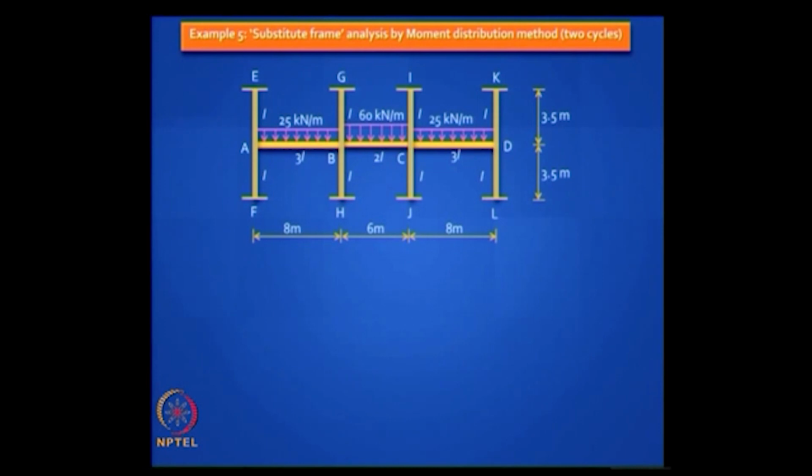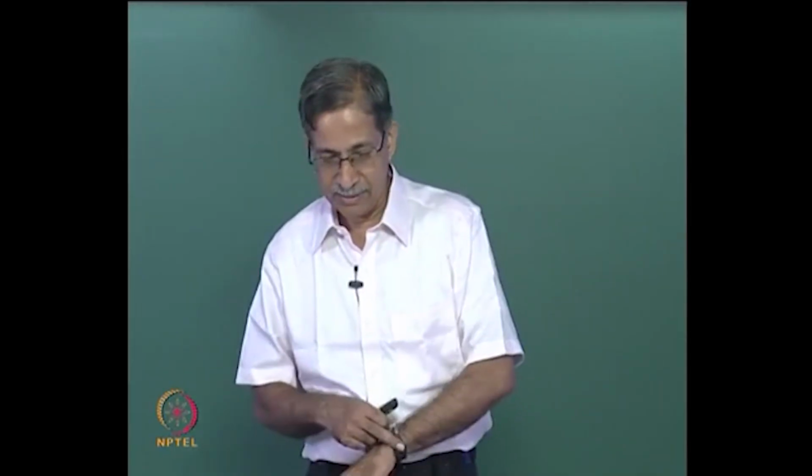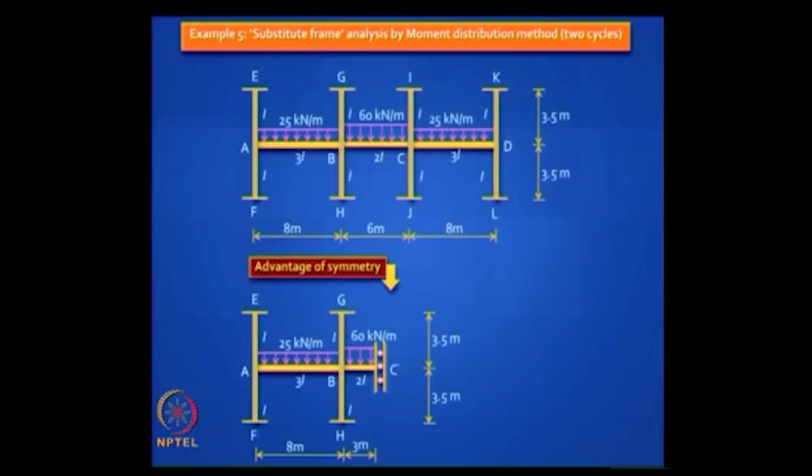So that is what this is, for example, what you can do in a 3-bay multi-storied frame under gravity loads, not under lateral load, because under lateral loads it will sway. Now I made our job easier because I have deliberately chosen a symmetric loading condition, in which case you can take further advantage and cut it in the middle, and what do you put there? Guided fixed support, okay, guided roller support, and you know very well how to analyze this.